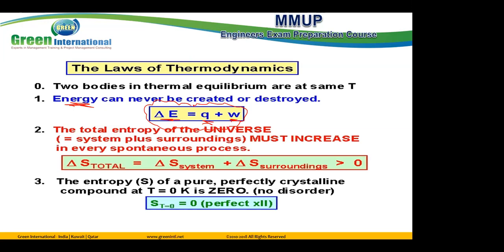But can I apply the first law of thermodynamics for this case? Yes, you can apply it. No problem. Change of energy, delta E, equals Q plus work. There is no restriction against applying the equation. You apply it and you get an answer. No problem. Whatever the answer refers to, you get an answer.